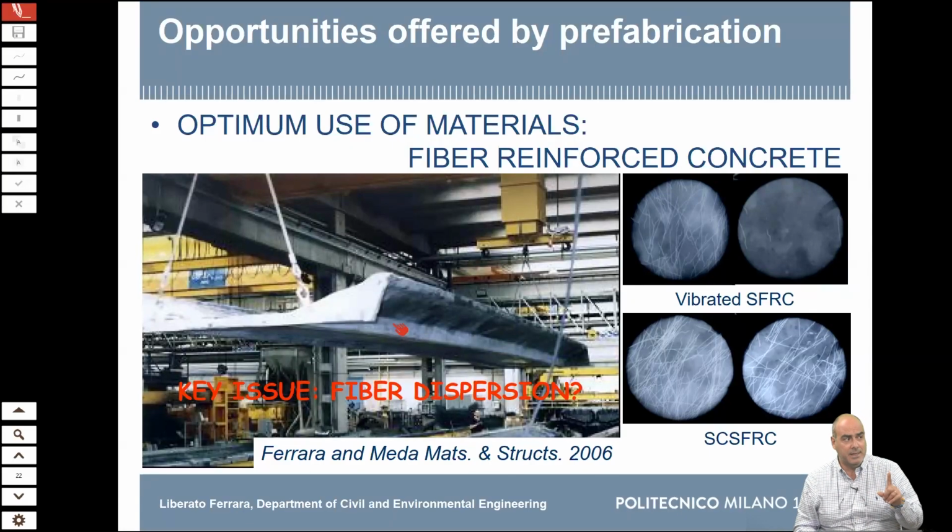This is another important thing in precast structures. You have to check not only your concrete, you have to make load tests on your elements. In this way, you also check how reliable your design is. That is a very important fact that we can have in precast structures. When we tested this element, we had an unexpected failure of the wings. So we started asking, why?